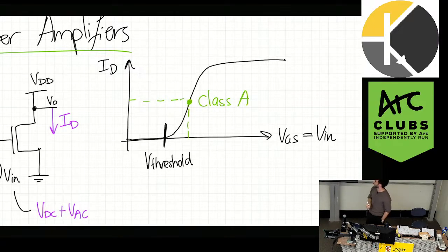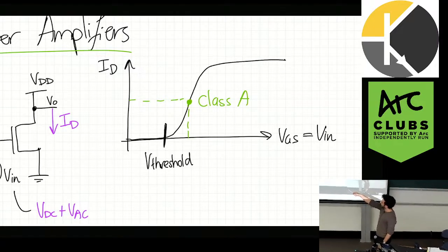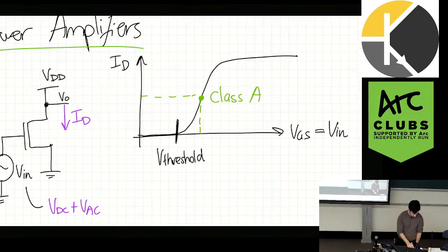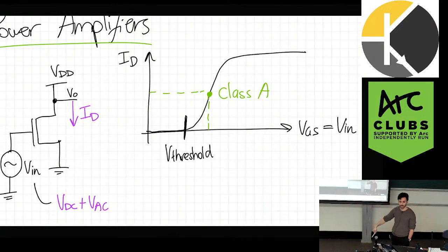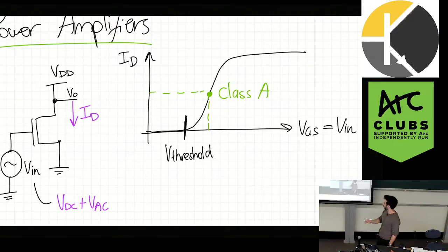Again, in the absence of any resistance, if I now start to swing this gate voltage, what point does it swing around? The bias point, right? So again, back to the valve example. I've turned it halfway. Now if I start turning it back and forth, it started as on. I turn it back, less water, more water. But in both cases, it's still on, right? Even if I left it, it was still on.